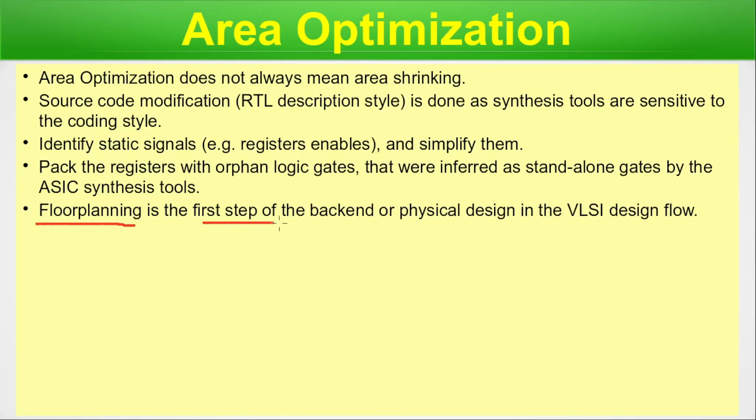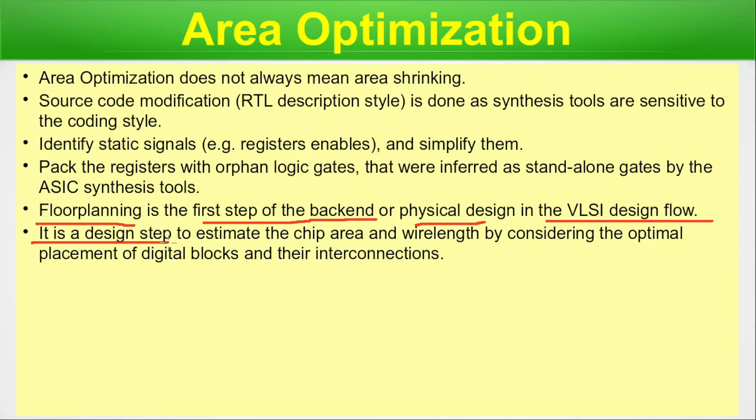Floor planning is the first step for the back-end or physical design in the VLSI design flow. As I have mentioned in the video description, you will find our full episode on physical design. There you will have the details why this is the first step. Next, it is a design step to estimate chip area and wire length by considering the optimal placement of digital blocks and their interconnections.